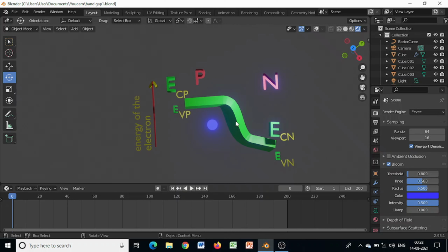It is also required that occupied energy states exist on the side from which the electron tunnels, and also allowed empty states exist on the other side into which the electron penetrates at the same level. These are at the same level.